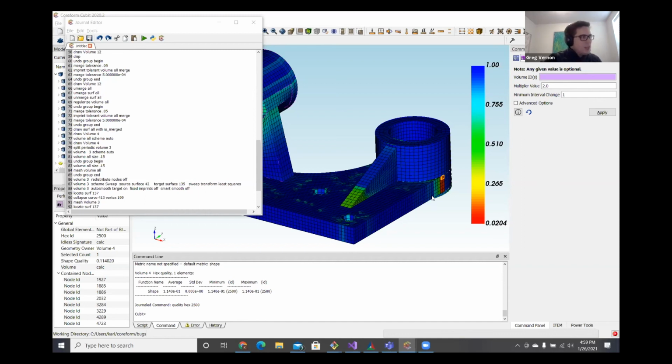That engine is not as powerful and robust as the ACIS kernel, which is licensed from Dassault Systems Spatial Corporation. So not all operations are supported with facet-based geometry. Some of the features are just hidden behind developer commands, but it does reflect that when you're working with facet-based geometry there's just not as much robustness there.